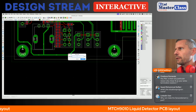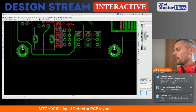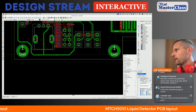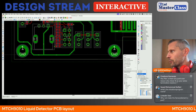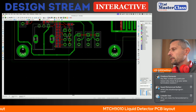So fillet. What will be the radius? 4.5, because we placed the mounting holes 4.5 millimeters from the corner.